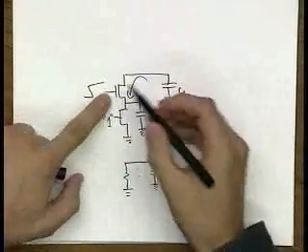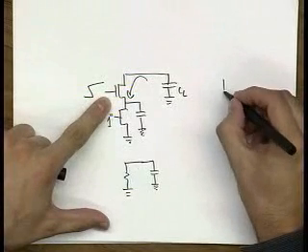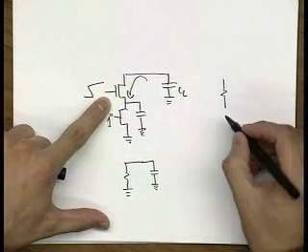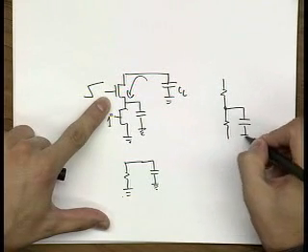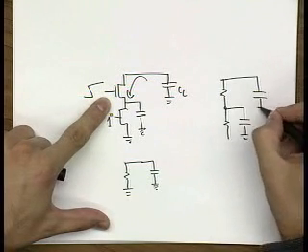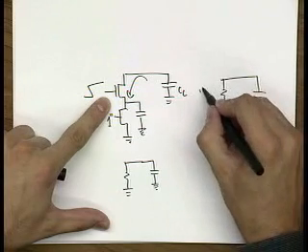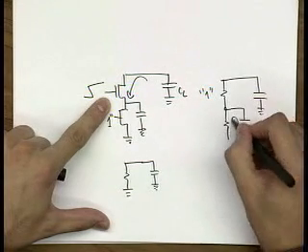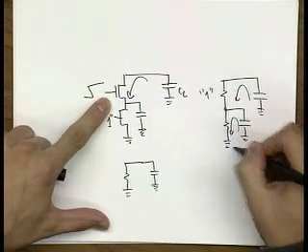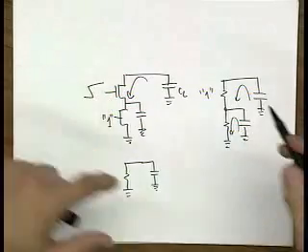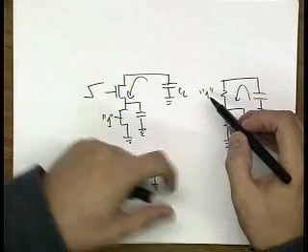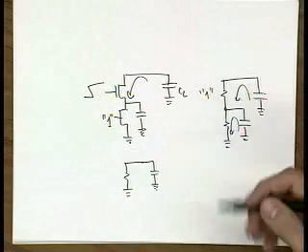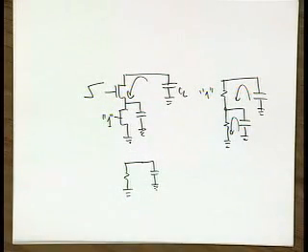Versus the case when the other one was 1, then you have to discharge both of these capacitances, this guy and this guy. And finally, in the last case, you're also going to spend some time to establish this one, because it's not 1 to begin with. So you have to spend some time turning that transistor on, resulting in an even longer propagation delay. Okay.